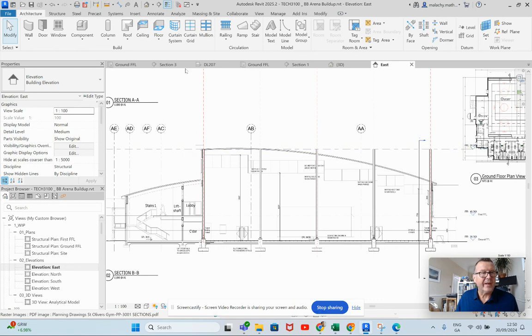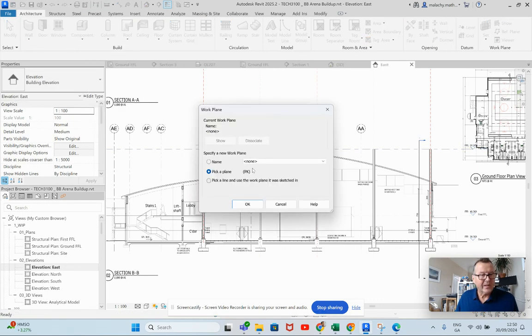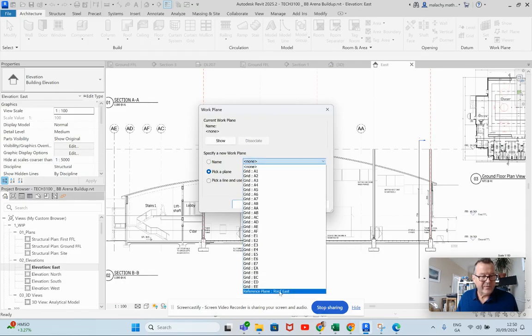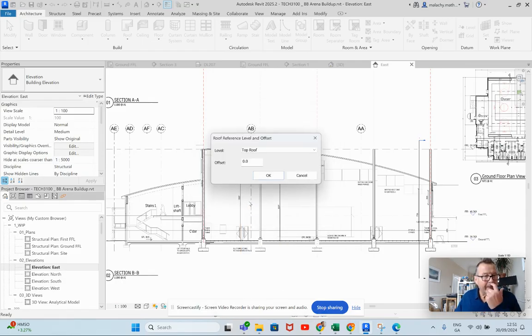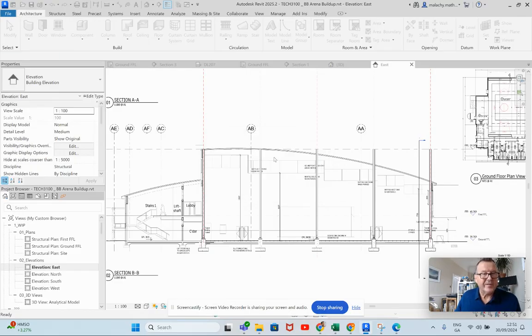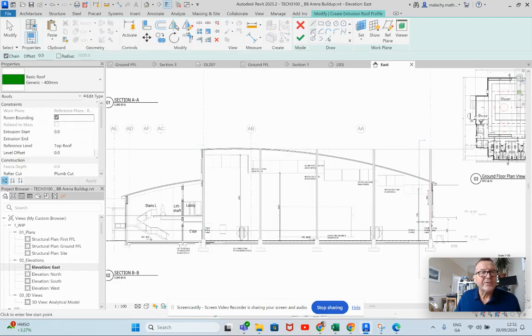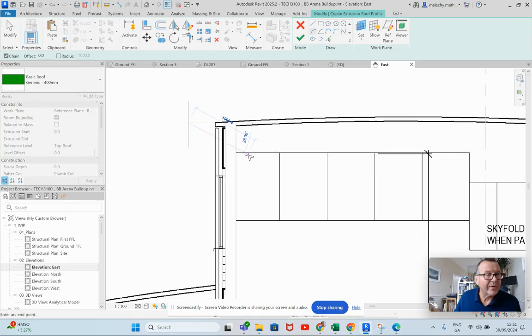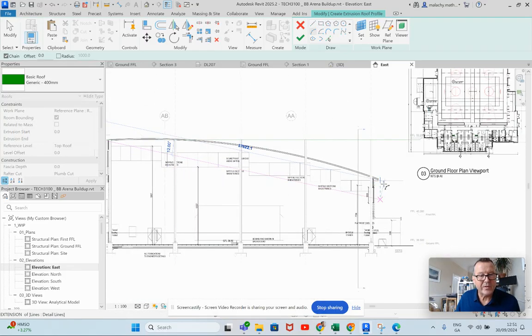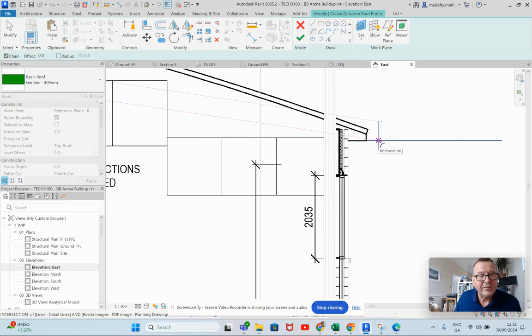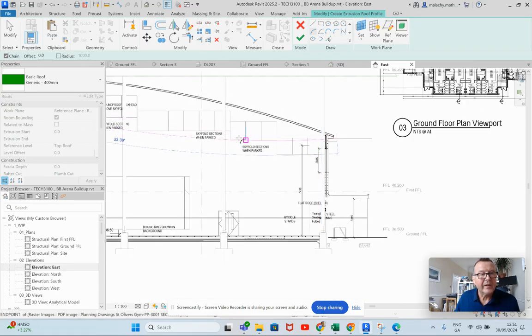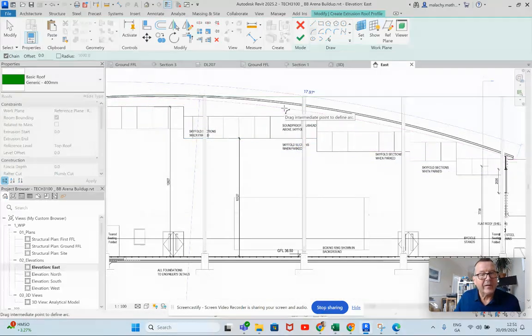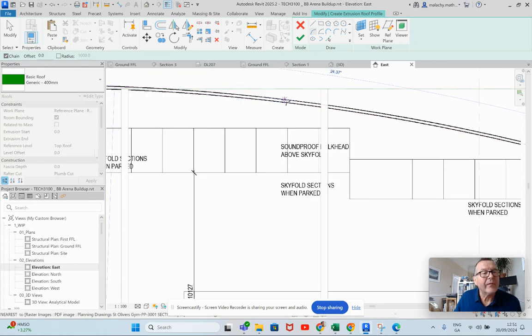Now we go through that again. So it is architecture, roof by extrusion. Pick the plane, and here it is, the roof east. Okay. And the level is the top, that's fine. And we're going to use this one here. It's the start end radius. So I'm going to start from the intersection of that point, that level, 1200 out, to this level, 1200 out. Okay. And I will move this up to the top one, I think.